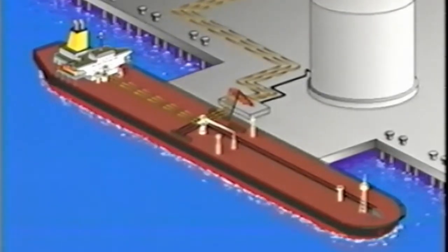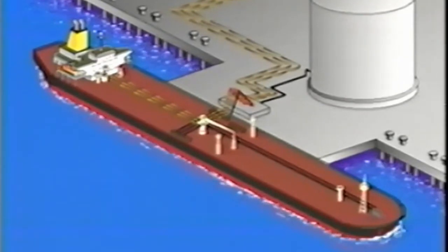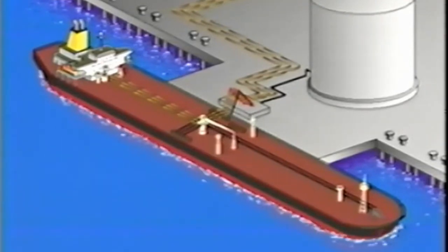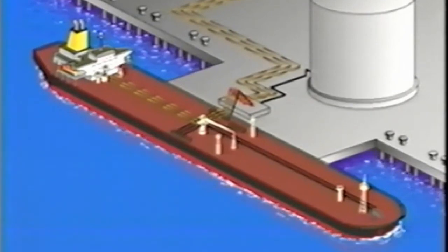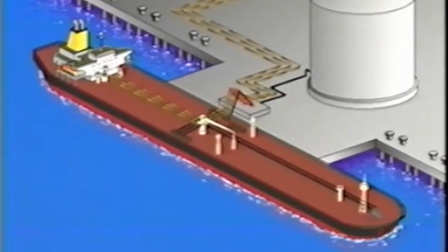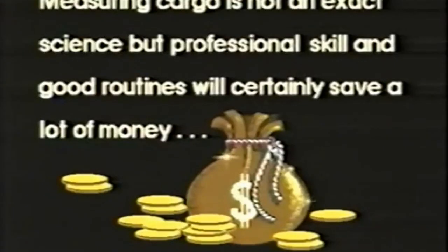To be able to do this, you must know the vessel's experience factor. Different companies and charterers use slightly different methods to compute this factor. Principally, it is the ratio between ships and shore figures obtained by comparing the results of a number of actual loading operations. Remember, measuring cargo is not an exact science, but professional skill and good routines will certainly save a lot of money.